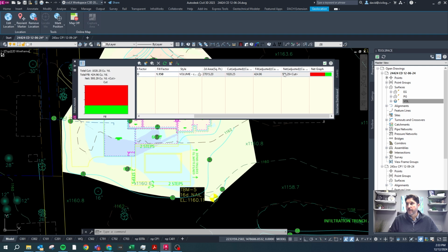So now we've cut a little bit too much. We'd like to take this back down a little bit, but now we know exactly how much we want to change. So if we get back to 200, we have the house on a crawl space like the contractor told us. We go from 600 to 200, so we want to change 400 yards again. 400 yards times 0.08 acres is 32 divided by 1600.